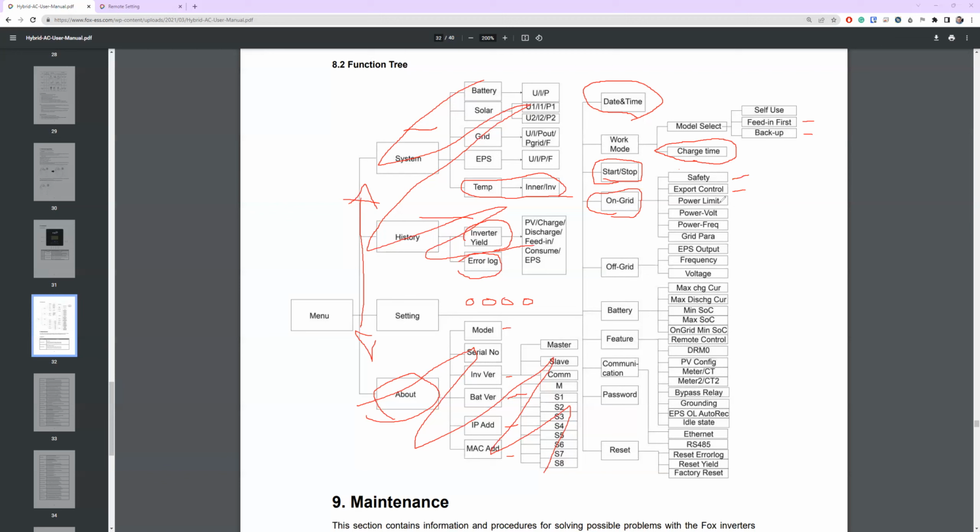So you might have 5 kilowatts worth of solar with a 5 kilowatt inverter, but the DNO, when you applied for export permission as part of your G99 application, have actually said, no, sorry, the local infrastructure can't handle that. We're going to limit you to 3.68, 3.69, 3.7, whatever they tell you your limit is, or lower. That's where your installer is going to set an export control. This is going to set how much can be exported at any one time. The rest will be put into the batteries, or it will just start to throttle the solar production to make sure you don't go over that export limit.